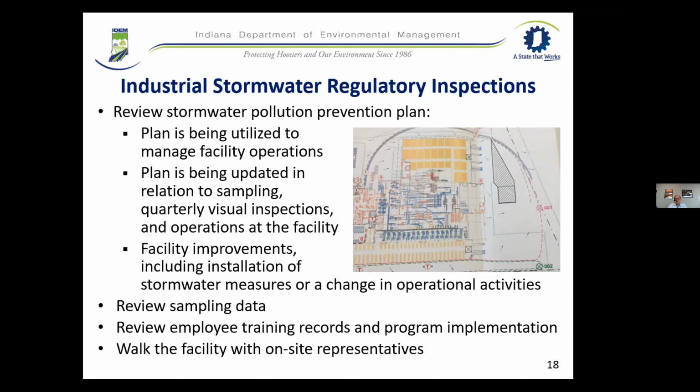And then we're going to walk the facility with the on-site representatives. Not only is it important for us to look at the data, but we also just want to walk that facility to see and observe the operations on site, the outfalls. Is there any staining? Do we see any outfalls that are failing? We're going to do a pretty thorough investigation of the overall facility, which includes the overall operation, but also the points of discharge from that facility.